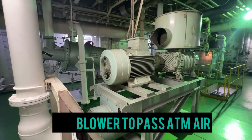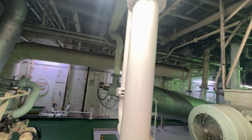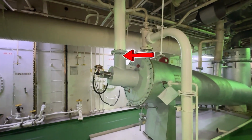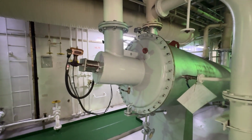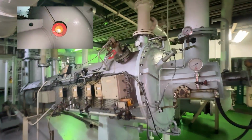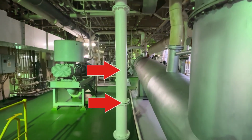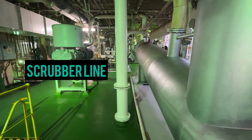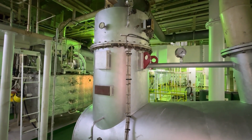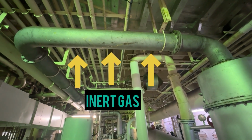So this is the giant blower which extracts atmospheric air and passes this atmospheric air into the combustion chamber. And this is where the combustion is happening. You can see from the side glass also to check the color of the flame. And this pipeline is the seawater pipeline coming from the scrubber pump to the IG chamber. And this is the demister which lets pass only IG, and the scrubber water will go overboard through gravity. From the demister, this IG will pass through the pipeline